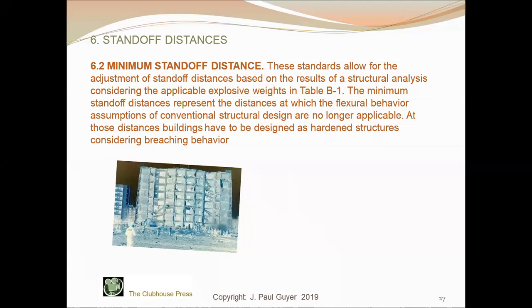For new buildings, even if such an analysis suggests a standoff distance of less than those in the minimum standoff distance column of table B1, standoff distances less than the minimum standoff distances are not allowed because those distances can be readily accommodated in building and site design.